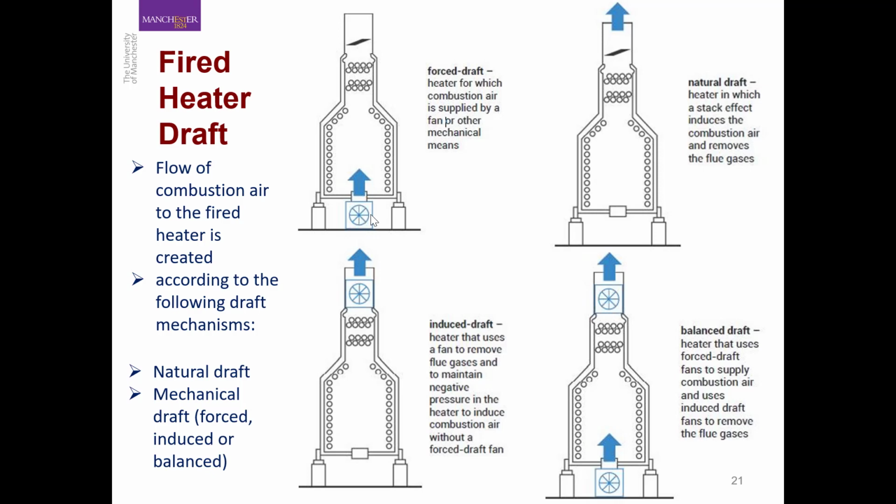Okay, comparing the inlet fan versus the outlet fan. So the inlet blower or fan will be much cheaper because you are just pushing air at a much lower temperature compared to the temperature of the flue gases here. And finally, you have a configuration where you are using two different fans, so one fan at the inlet of the air and one fan for the outlet flow rate of the flue gases. And by using two different fans at the inlet and outlet, you are in a better situation to regulate the flow rates of inlet air and the outlet flue gas.